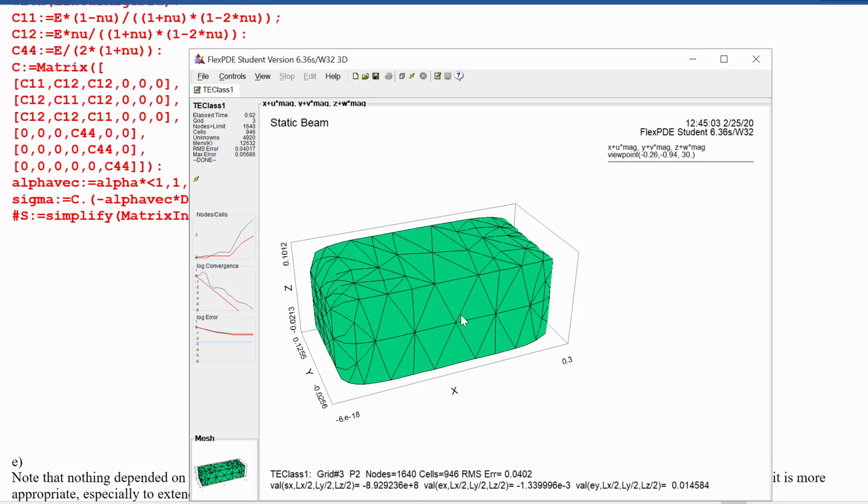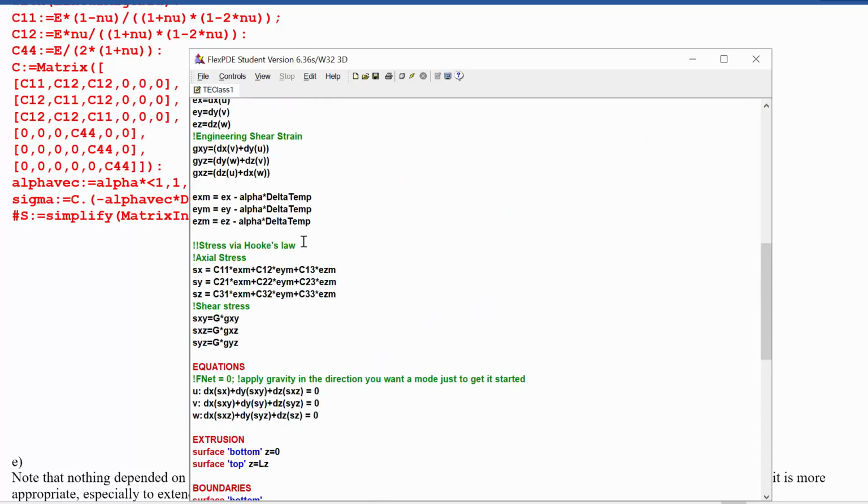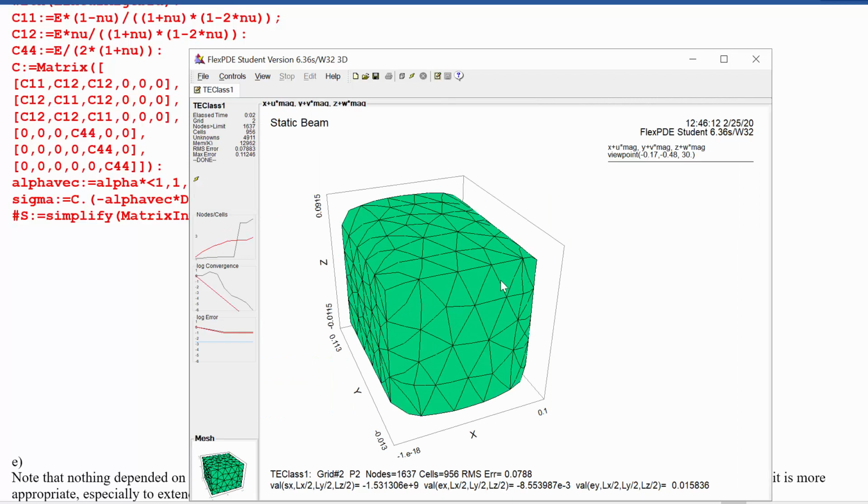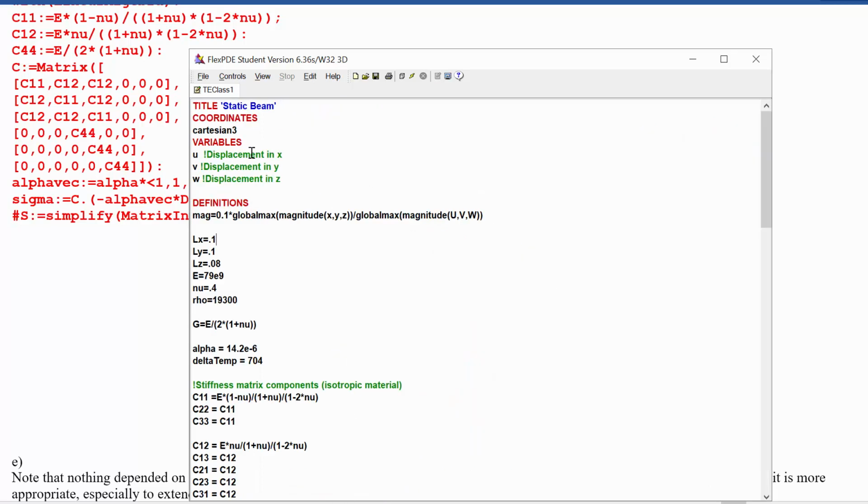Now here's some other changes we can make. If we make this smaller in X, then the anchors, let's say the wall fixed supports, are going to have more of a bearing. We expect this to go up somewhat. We can change the X length to maybe 0.1, yeah. And now it's a cube. Now holding it at the walls makes it a lot closer to just holding it completely still from moving in those directions. We've got a 1.5 gigapascals there.